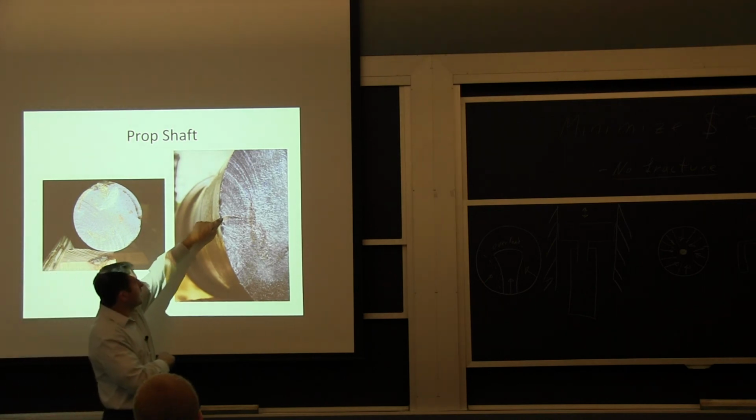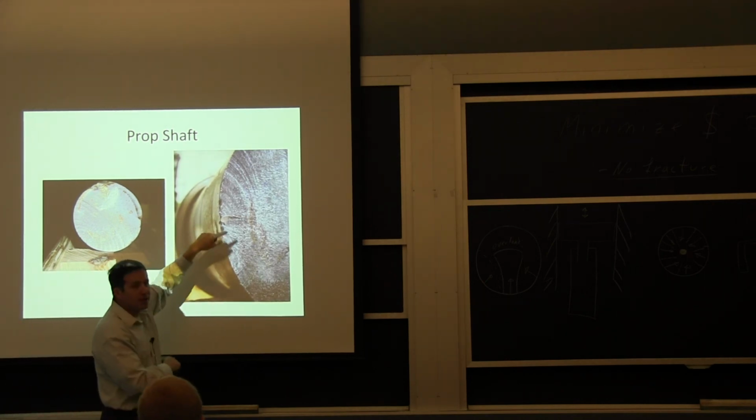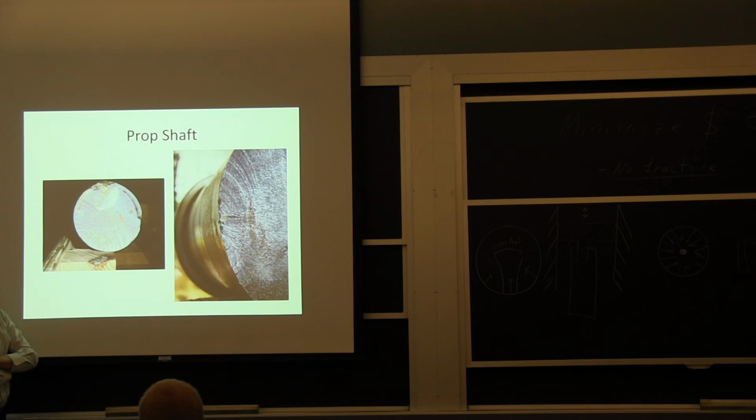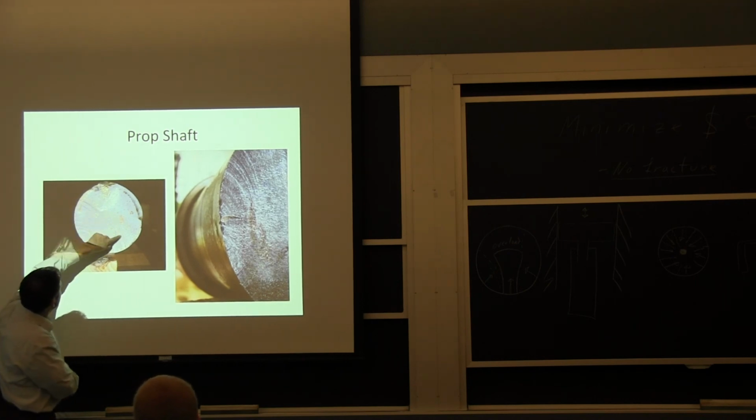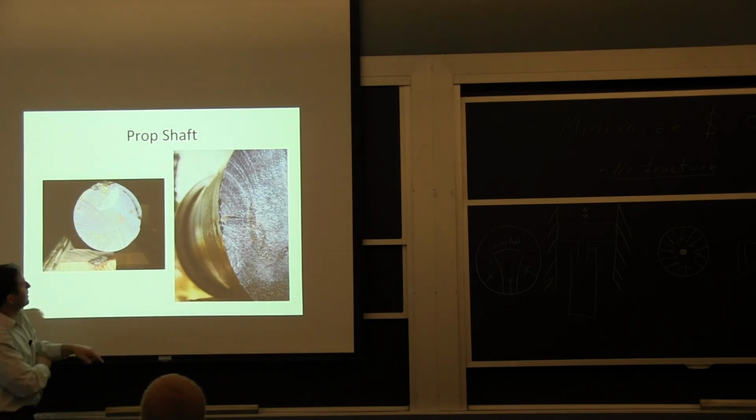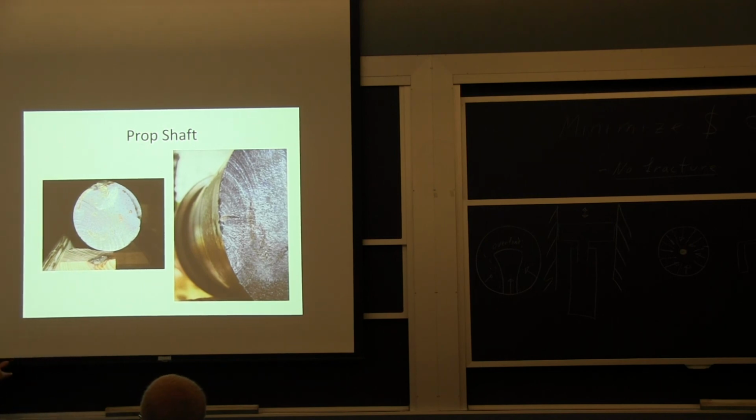And this crack propagation line allows you to narrow down exactly where it started. And you can also infer something else. If you start from here, definitely up to here, you had a 7-inch axle that had a crack halfway through, and it was still holding on.